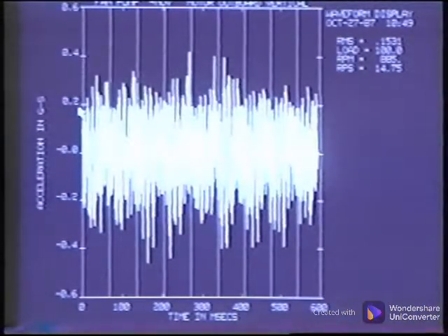One look at the waveform and we see it is not anything like the waveform energy due to unbalance or misalignment. Instead, it is very complex and busy, with non-repeating or random impacting energy. This energy is from a looseness condition that is causing components to rattle against each other, creating many frequencies.